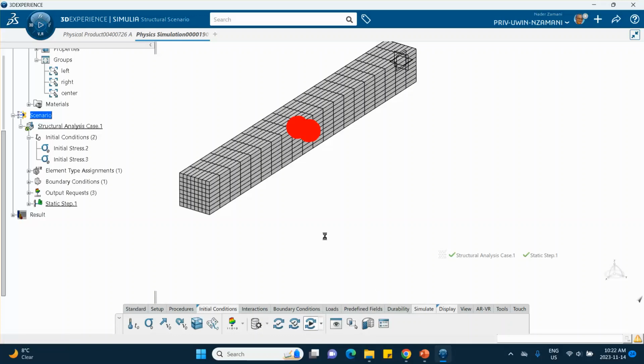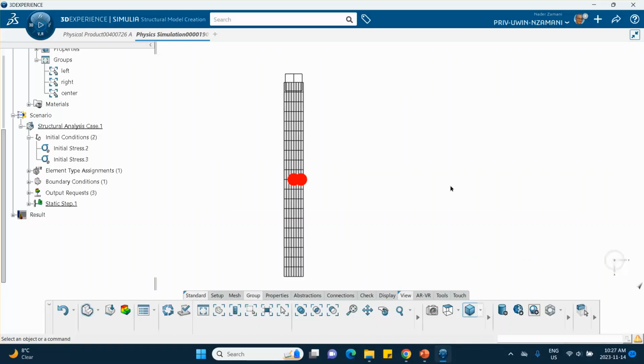So this will actually bend. If you look at the view from the top, I have already deleted the compressive stress on the left set of elements. There is compressive stress on the right side, and there is more tensile stress in the middle. That's fine. This is the clamped end. So there is no equilibrium between the initial stresses, and this is going to deflect. This is going to warp or deflect or move so that it tries to equilibrate that.